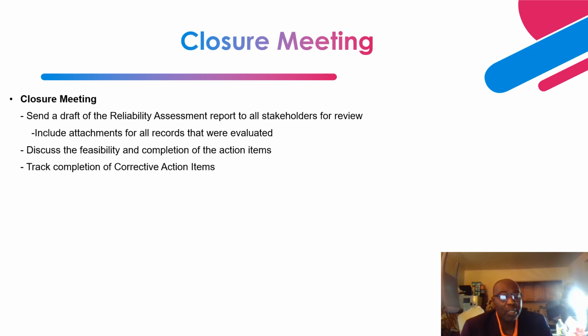You evaluate the capacitance, high voltage to ground, low voltage to ground, and high voltage to low voltage, against what is on the nameplate and the factory acceptance testing results. Very important. That will tell you if there's a significant change in capacitance, which tells you that the insulation system has deteriorated, or that there has been a change in the arrangement of the insulation system.